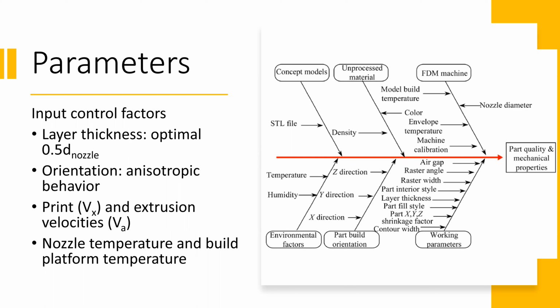However, if the layers are less and they're thicker, then this means that the staircase pattern from the layers will be more prominent and thus a lowered surface resolution. On the other hand, if the layer thickness is decreased, the accuracy and the geometry of the structure is increased, but then so is the build time. Theoretically, the layer thickness can range from 0 all the way up to the diameter of the nozzle, but the most optimal layer thickness would be 1/2 of the diameter of the nozzle.